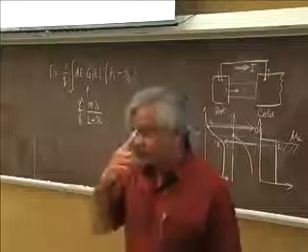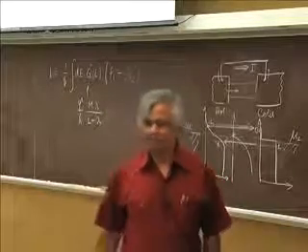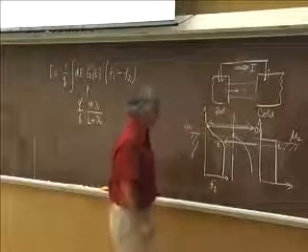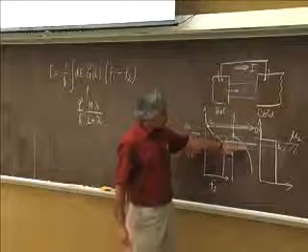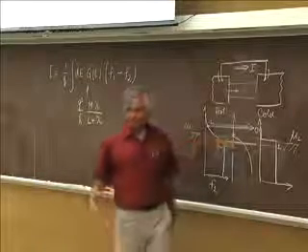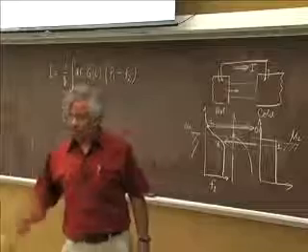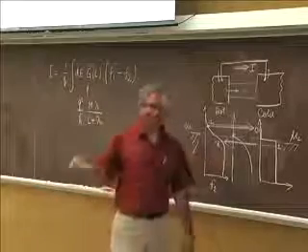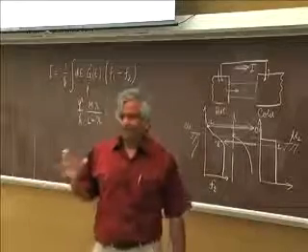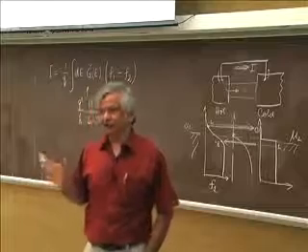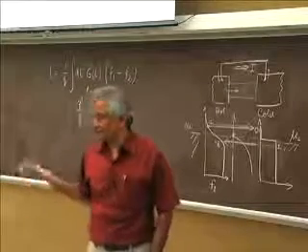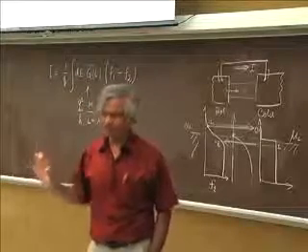Now, usually when you talk about thermoelectric effect, sometimes people say that the reason this is reversed is because in the case of the valence band, it's actually holes that are moving. But I feel that's really not a convincing explanation because finally in all solids, what moves is electrons.